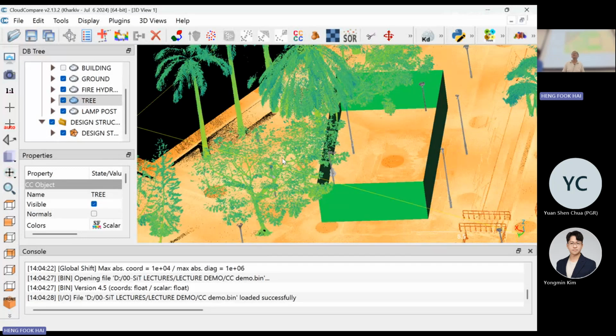I think how an engineering company uses some of this survey information is that once the surveyor goes down on site and gives us sufficient resolution to work with, that's when we start to do our feasibility study. Say we need to construct a structure here, what are the things that we need to move out of the way? What are the costs of some of these diversions of the services and diversions of the lamp posts? And after we take it out, do we have to reinstate it back after we're done? Most of the time, a lot of the decision making is brought back to the office to be discussed and mapped out.